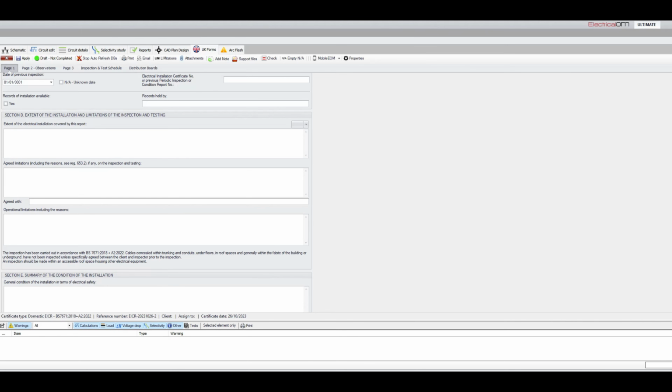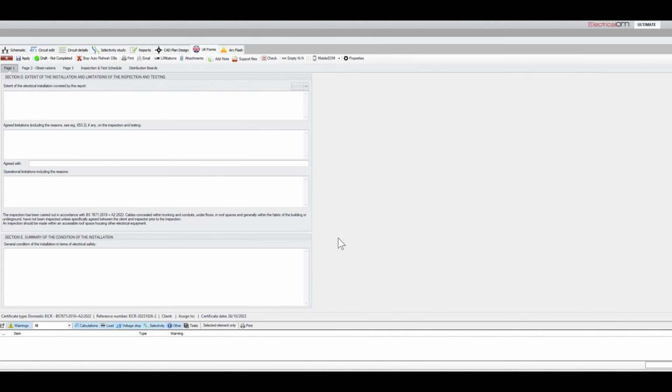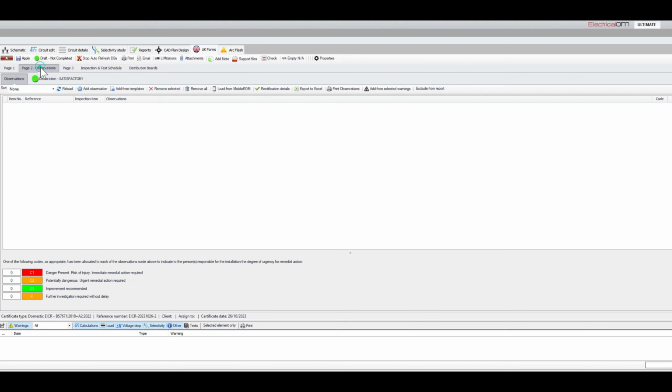And we could make note of an issue around our insulation resistance testing and the approach we're taking as regards that as well. But there's also space on the actual test sheets where you can make note of that as well. So you can make an observation on the general condition of the installation. So if you want to summarise what you've seen into a paragraph, the more information the better, as long as you're setting out exactly what you have been doing.